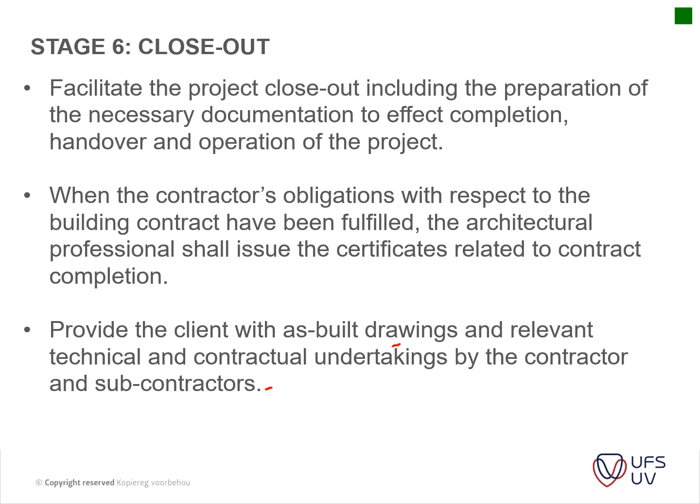If it's a public project for government, you would have an occupation certificate, like for instance your health and safety, or your health inspector will come and inspect your building. They will ask, is the structural engineer sign off on all the SABS documentation, is the electrical COC in place, etc., etc.